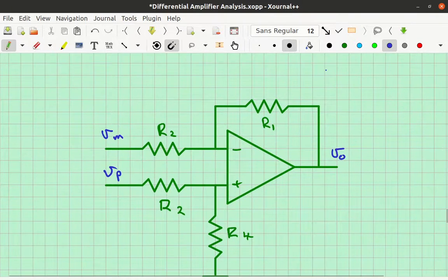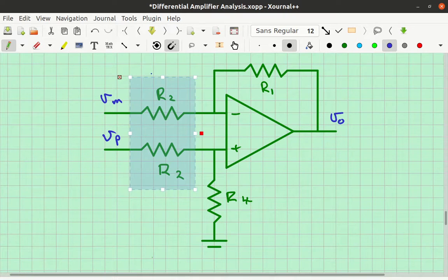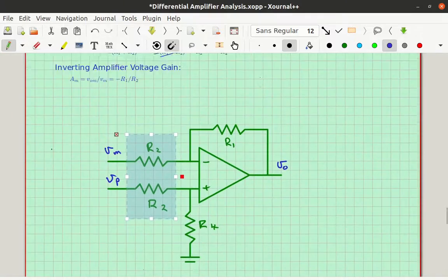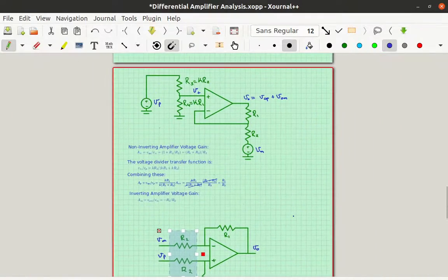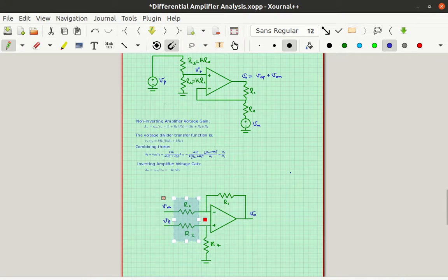Now normally we don't see the circuit written that way. We normally see it written this way. And we normally pick the constant K to be 1 so that we have a nice symmetric thing on our input resistors right here. So if you notice, this top circuit here is the same as the bottom circuit. This bottom circuit is just redrawn, and we picked K equal to 1.